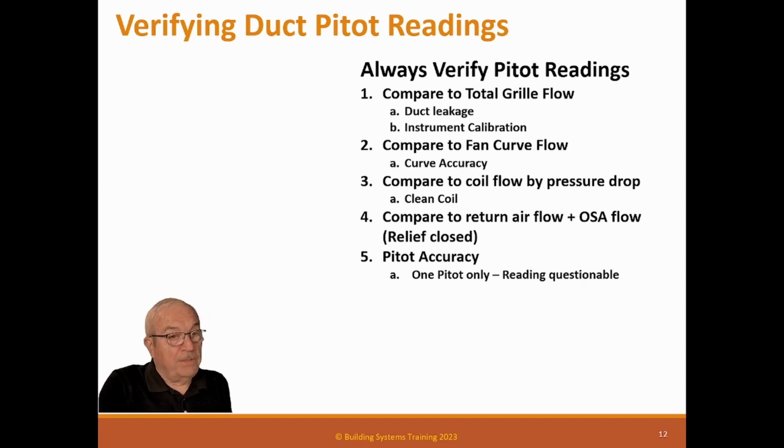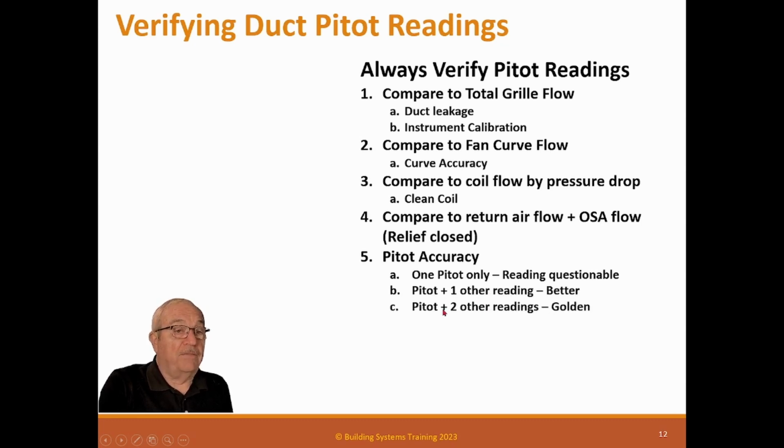If you take a pitot and that's all you have to verify this unit flow, then the reading is questionable. If you have the pitot plus another reading that verifies it, you feel a lot better. If you have the pitot plus two other things, you're absolutely sure that your pitot is accurate.